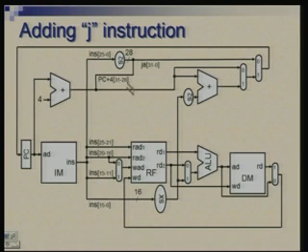So the program counter PC has 3 possibilities: either plain PC plus 4, or this PC plus 4 plus offset, or this combination of PC bits and instruction bits, right. You can actually combine these two multiplexers into a single 3-input multiplexer. That is another way of designing, but we will just retain it in this manner. Now, the next thing is to start worrying about how we are going to control this data path. What are the points where we need to apply control signals? That is what we will see next.